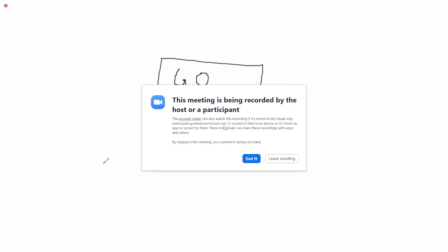Now you tell me, if you touch P and N, I should not use this word touch. You should not touch electricity. Never do that. Never. Even while working, try to work on the cold thing. Cold means switched off. Breaker must be off, supply must be off. Try to work when supply is not there. Only in emergency we do that. We can do it because we are experienced. But to you, my advice is try to work after switching off, and even make sure that nobody switches it on when you are working. That also you should make sure.